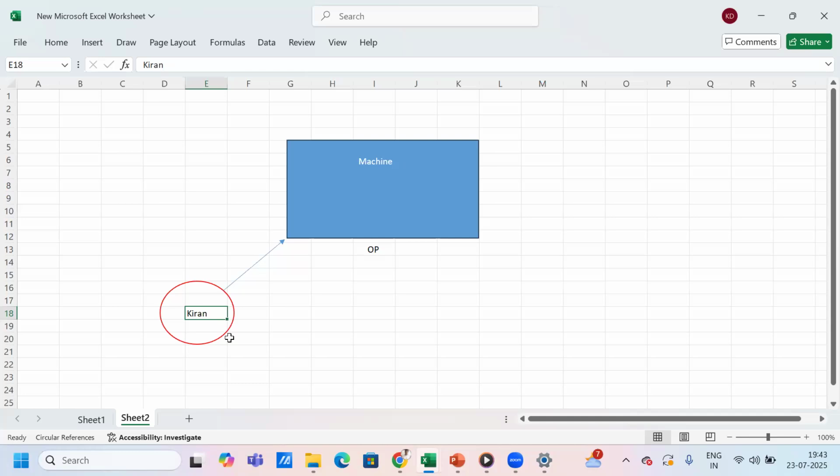Then I observe the 3D abnormalities. Yes, I observe that the operator is bending. There is a lot of burr being generated. There is a lot of coolant leakage. The operator is finding difficulty loading the job. There is a very low light level on that machine. There is some danger condition, a wire is open. On the machine there is a jerk, and there is some abnormal noise.